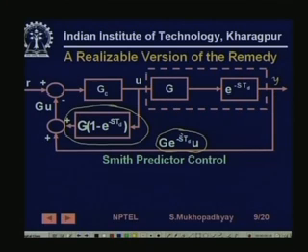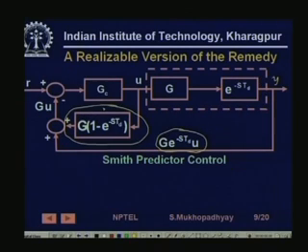On the other hand, now you see that if this is a big if, but if I knew g and td very accurately, then there is no reason why I cannot simulate this transfer function and then feed it by u. See, u I have because it is coming out of the controller. So I already have it, the controller is in my machine only.